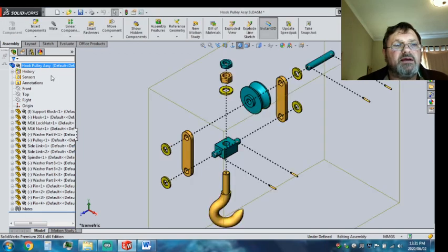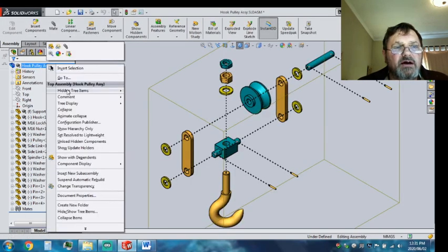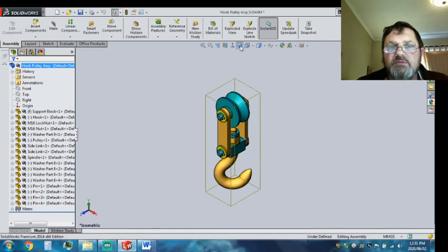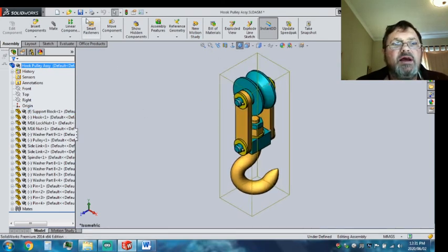And I can go back there. So then I'm finally going to go collapse because my job's finished. I'm going to zoom it up a bit and I'm going to save it. Now my exploded view is in the same assembly file. It's not in a separate file. You can't have one assembly file for collapse and one assembly file for explode. It's all in the one file, or else you won't have all your marks in one place either. Some will be in the dustbin and some will be in your pocket.